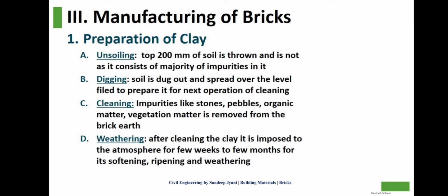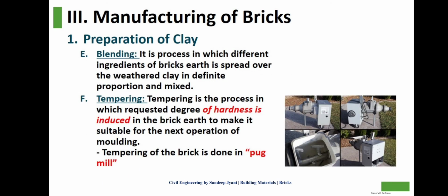Weathering. After clearing the clay, it is exposed to the atmosphere for a few weeks to a few months for its softening, warping, and weathering. Blending. It is the process in which different ingredients of brick earth are spread over the weathered clay in definite proportion and mixed. Tempering.